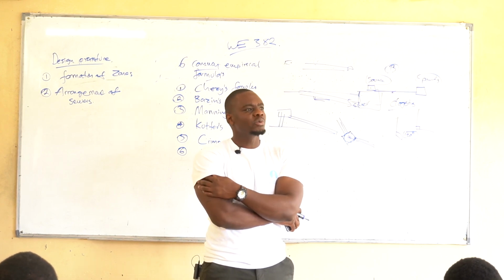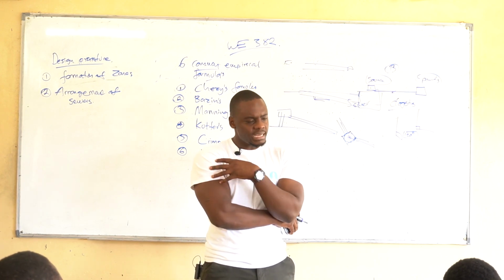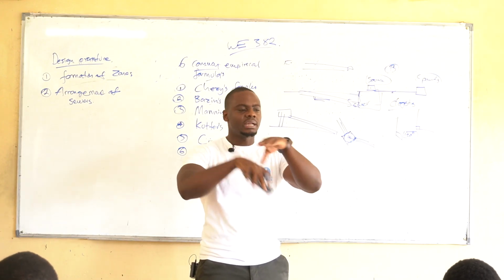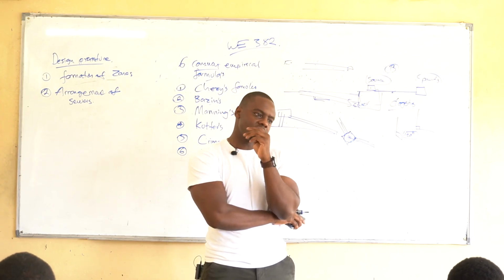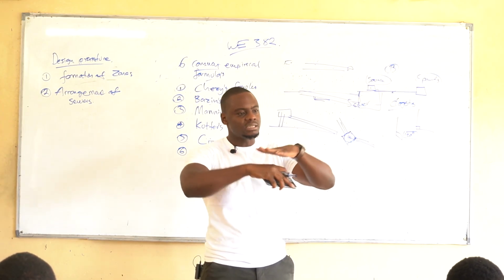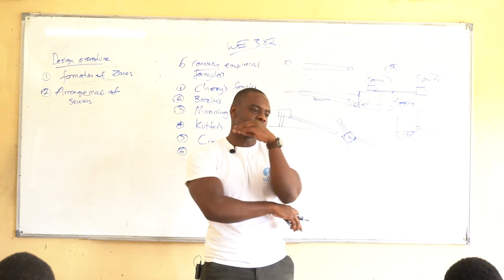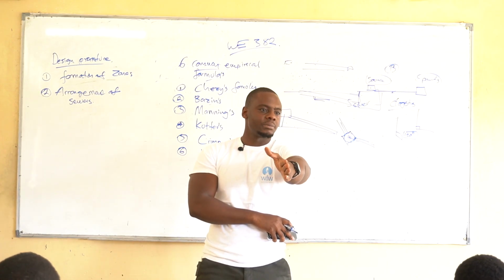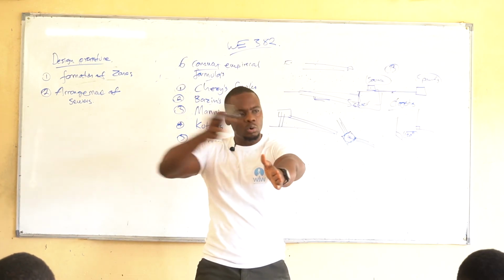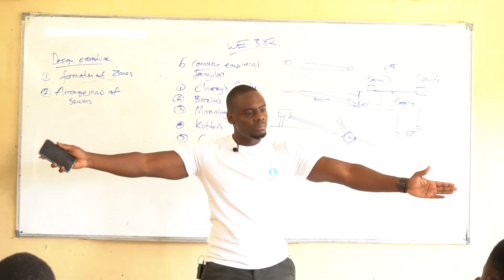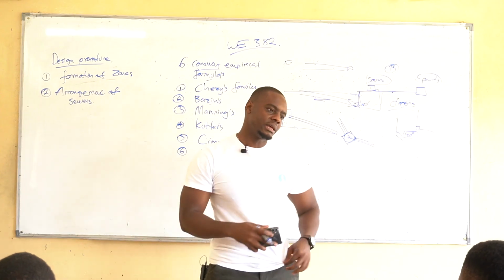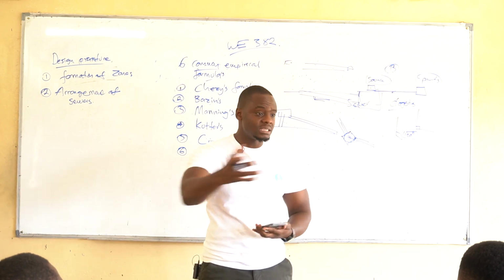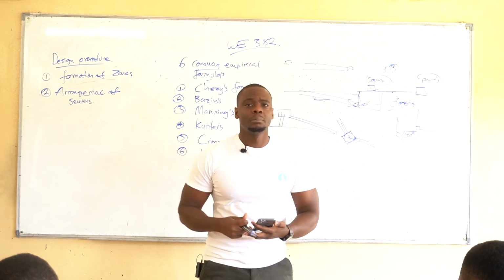Wait a minute, people are way too happy here. What could go wrong? That's us. So if you put a sewer and a water line like that, there are always leakages. Water could easily interact, and that is bad. So if this is where your water line is, then probably there's an angle that you stay away from. You look at the other options that are there. So it becomes very tricky, especially for unplanned settlements like they are. People have already settled.